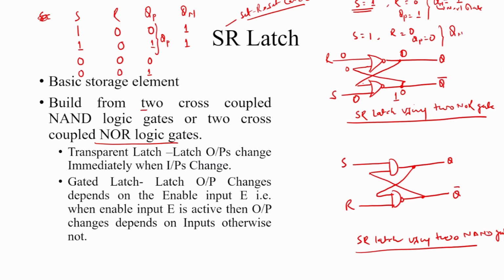And here when 1 and 0 go in, one of the inputs is 1, so this becomes high. Here S is 0 and Q is 0, so this becomes 0, 0, and the value of a NOR gate in the case of 0, 0 is 1, and this is 1, then once again this is 0. This means whatever the value of the previous state, this is also the value of the next state. What happens when this is 1, this is 0, suppose the previous stored value is 1? Then what will be the next state?